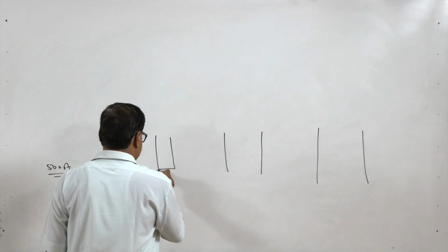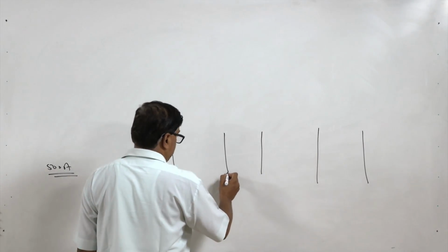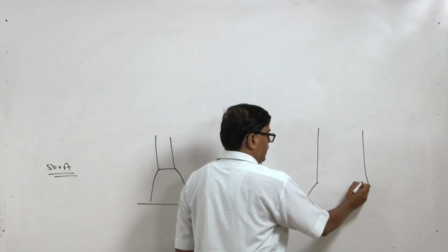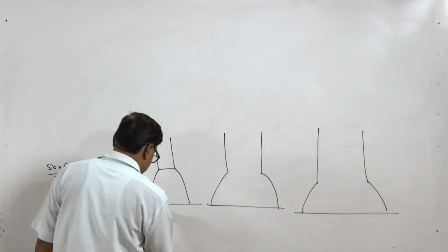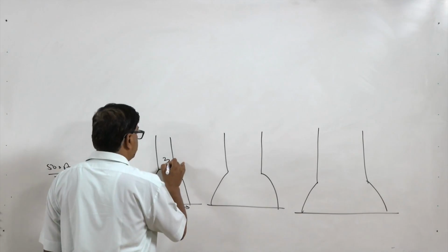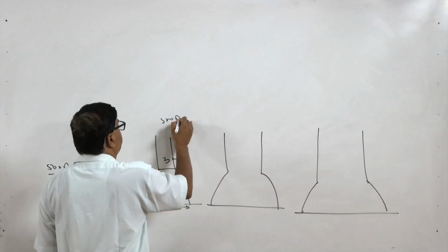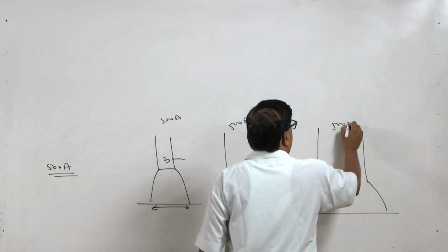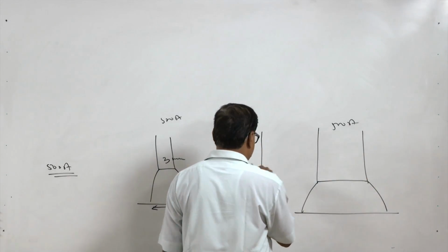So, the size of the arc changes like this and like this. Now you see the weld width here is this much in the case of the 3 mm size electrode. 500 ampere welding current is supplied in all these 3 cases.